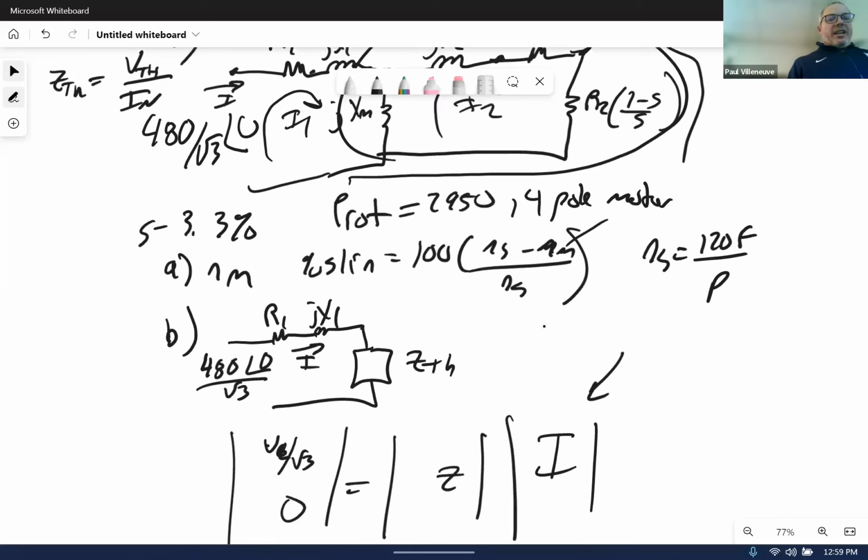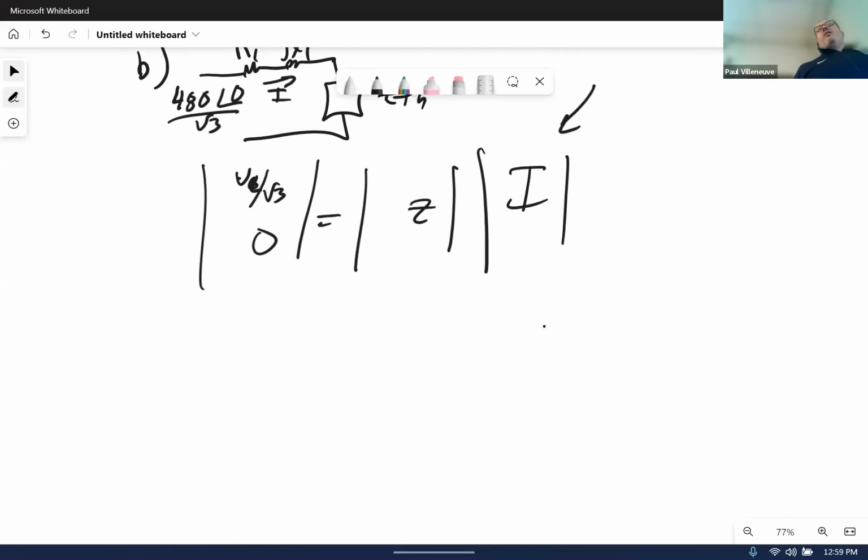So that's the stator current, and a lot of people forgot there are two parts to the current, right? There's the magnitude of the current and the angle of the current. We're in AC here. We can't just get by with the magnitude of current. You've got to know the angle. You may not always use it, but you've got to have the angle. If you remember the previous problem, it said 75 amps at a 0.85 lagging power factor. How would you have been able to do the previous problem if you weren't given the power factor? You couldn't have done it. It's not feasible.